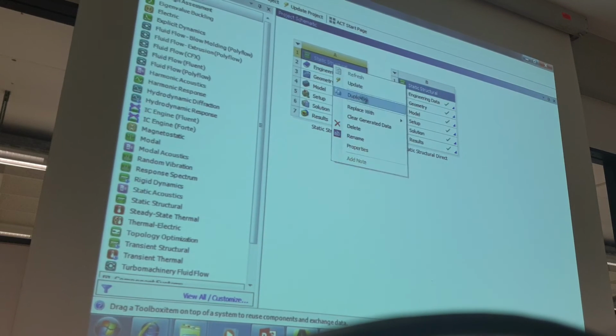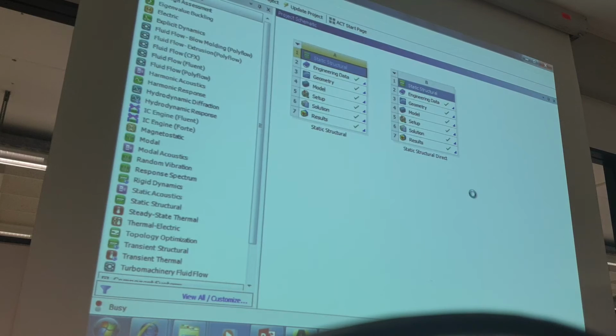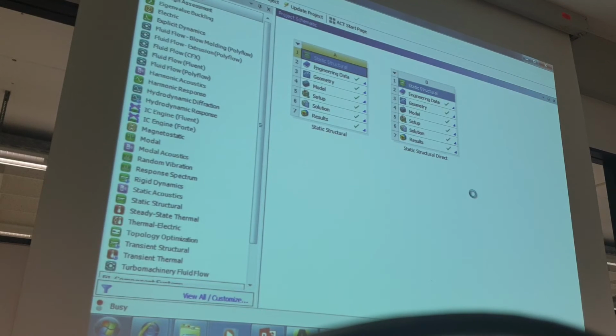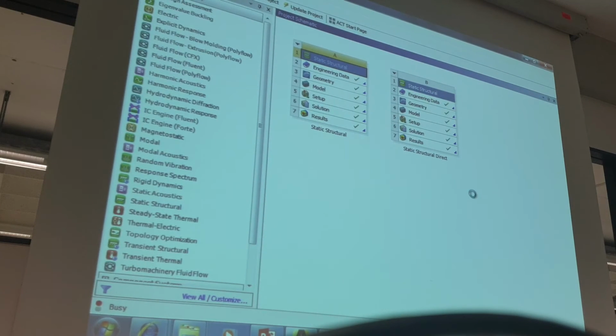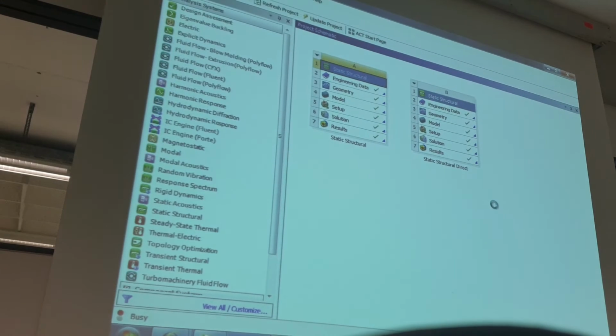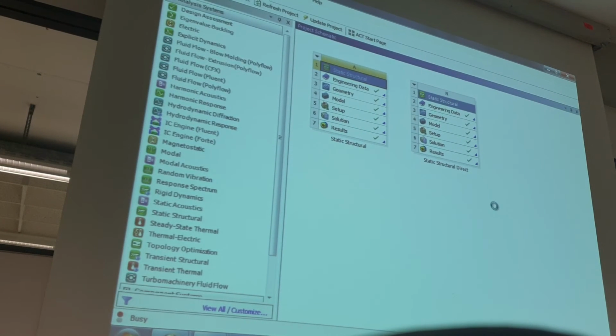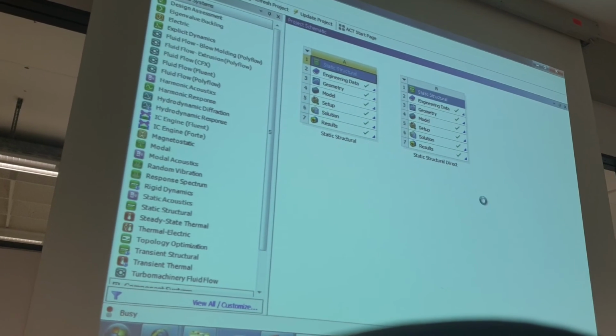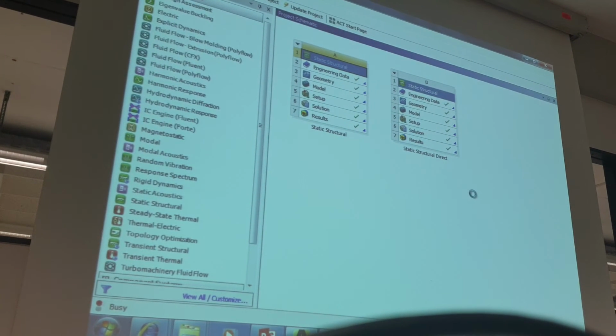I make again a duplicate of the first simulation, and we will say, okay, iterative solver was quick, yes, we stay with iterative, no problem. But what are we doing? We say now exactly quadratic for radius and linear for other points. It will be quick.